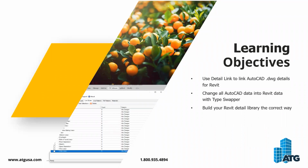How do you choose an appropriate scale for the view? Typically, whatever detail scale you're bringing in is the detail scale of your drafting view. So it's at scale, whatever your AutoCAD detail is that you're bringing into Revit. Hopefully that helps, right? And you can verify because you're going to be taking live dimensions, because everything is drawn at scale in Revit, whereas in AutoCAD, we're moving things to a scale.